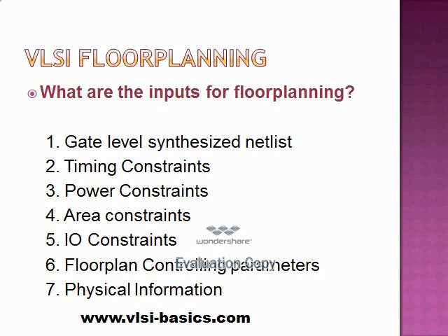Now, what are the inputs taken for the floor planning stage? The inputs are synthesized netlist, timing constraints, power constraints, area constraints, physical information, IO constraints, and floor planning controlling parameters such as aspect ratio, height, width, utilization, and row to core ratio. We can optionally provide macro placement and IO placement information to the floor planning stage.